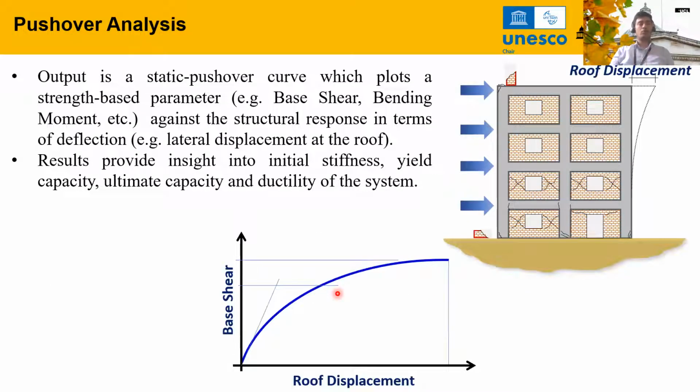So, the steps of pushover analysis. After we conduct the pushover analysis, we get a static pushover curve as shown by this blue curve here, which represents base shear versus the roof displacement in this case.